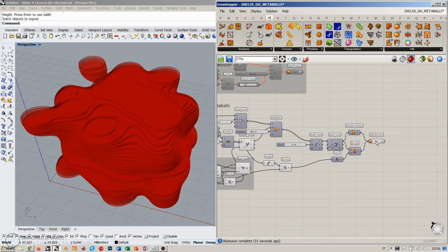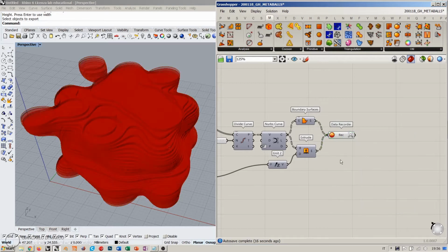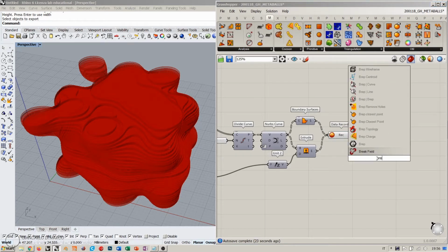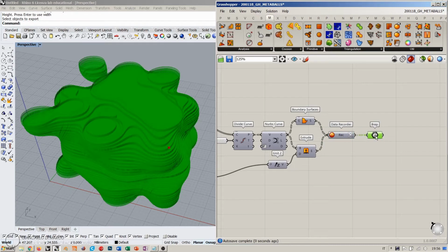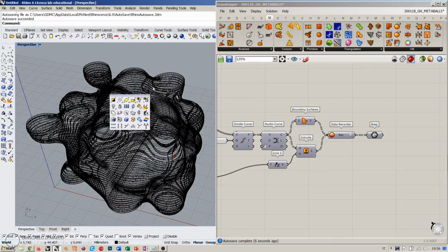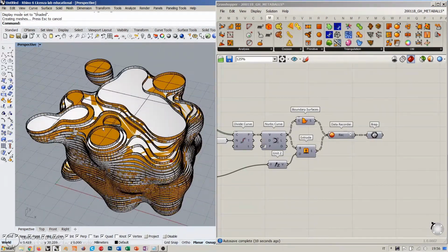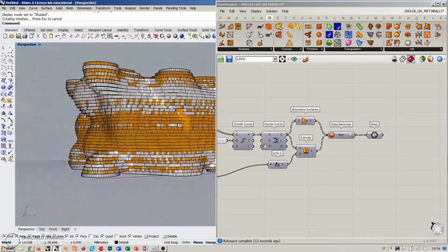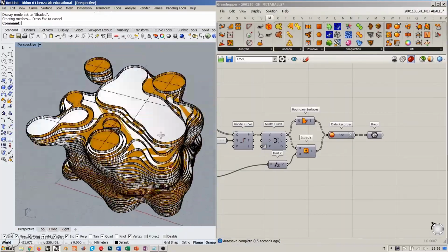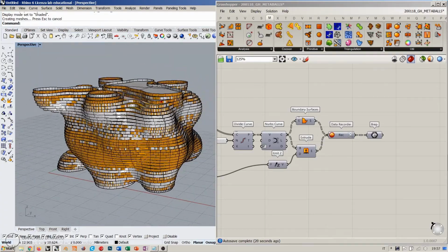And that's it. We have this nice set of... well, actually, these are surfaces, so in general, I would use a Brep in order to avoid any surprise here. And I'm going to bake these, grouping it, and here we have our set of three-dimensional objects. You see that this orange here is coming out because of inverted normals, but we can easily manipulate things in Grasshopper in order to have the proper orientation for our objects.